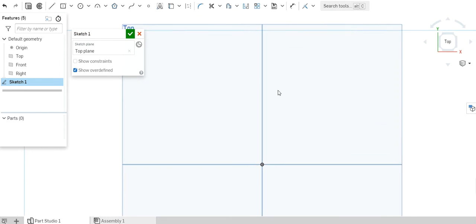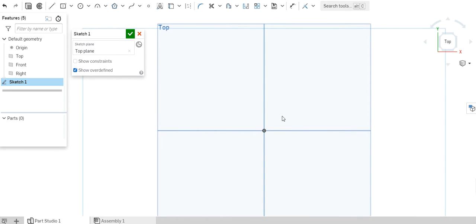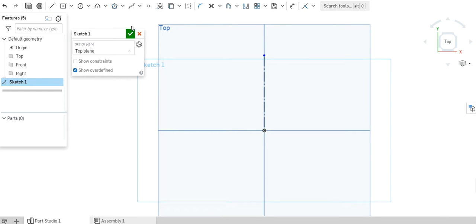Okay, so the first thing we want to do is figure out what the path of our corner is going to be. So I'm going to create a line, make it a construction line, and have it go straight this direction, and then exit off. Then I'm going to do that again at some other angle here. A normal corner would be that way, but there's already a corner, so let's do something different. Now I'm going to hit the dimension tool and select an angle between these two. Why don't we say 130?